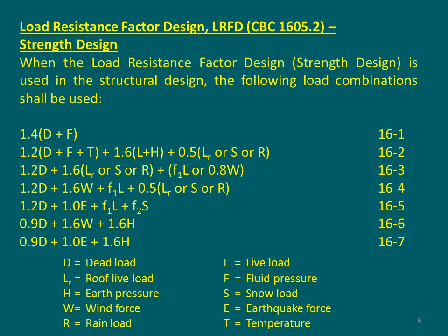In this slide, I have the load combinations for the ultimate load design. This can be one such as 1.4 dead versus 1.2 dead plus 1.6 live. This can be based on the California Building Code, which is based on the IBC, International Building Code.